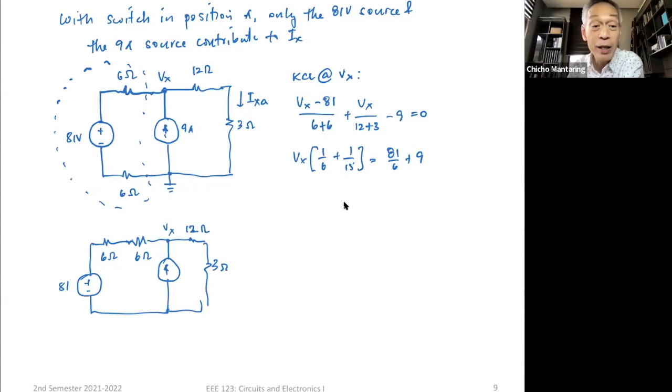No? Thank you for pointing that out. So, did you get that explanation? No? If I have elements in series, I can rearrange it in that branch, and it's not going to affect the current through the branch or the voltage across the entire branch.